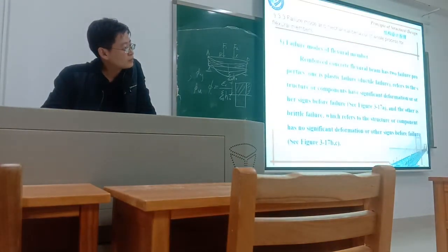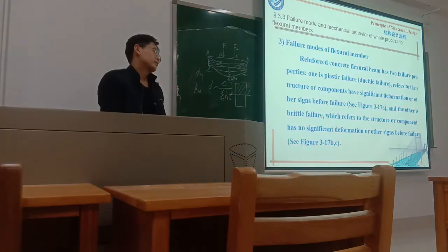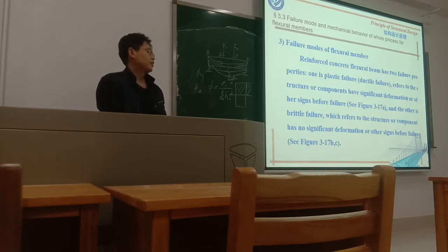Can we say that the reinforcement ratio of the appropriate reinforcement is larger than the minimum reinforcement and is less than the maximum? Yeah, it's between that space. Yes. And we can say that for the over reinforcement, the ratio is larger than the max. Yes. And for the under reinforcement, the ratio is less than the minimum. Yes.